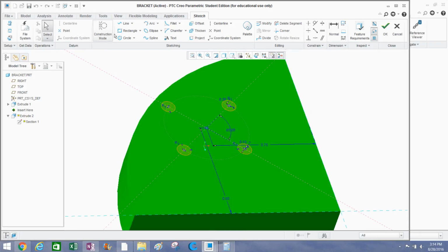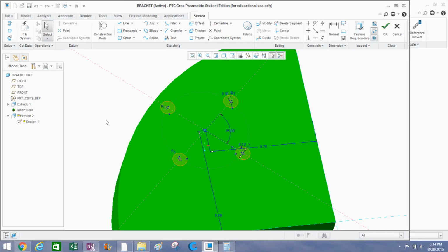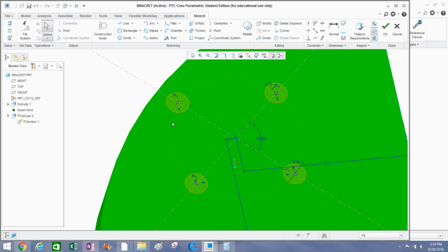they have this thing up here called construction mode, which is really useful. So this circle was made in construction mode. Basically, in the sketch, this doesn't have any effect on how you sketch it. So, like if you put a line in there, a box or something else, it would actually extrude the box. It kind of just uses it as construction. You can see it even says the word construction.